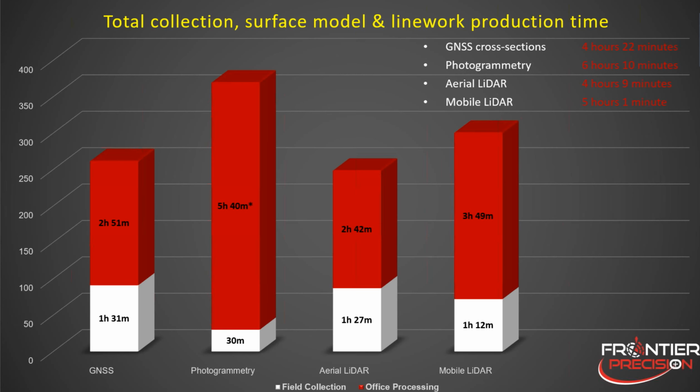So what we're finding as we do this is that on the office processing side, to create everything start to finish, there's not a lot of advantage one way or the other using mobile scanning or GPS. It's all pretty much the same. So where you really have to look is the data collection time, because we ran through this several times, and there wasn't one thing that jumped out as more of an advantage over the other in terms of processing the data.